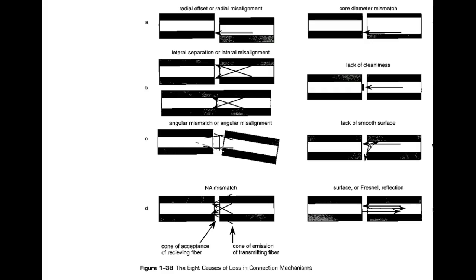Core diameter mismatch. So we're using diameters. This cable that I passed around has a blue surface and an orange coating on it, but it's 50/125. The cable we're using is 62.5/125. But they both have orange outside jackets, right? You understand that?